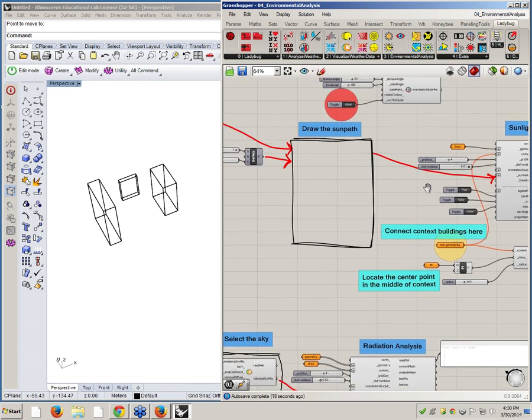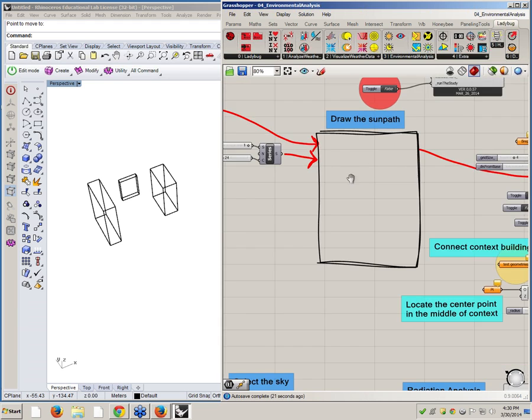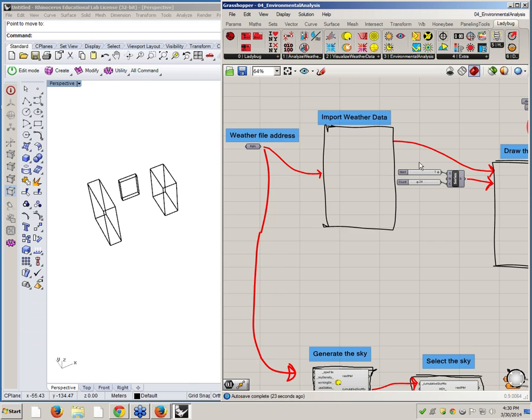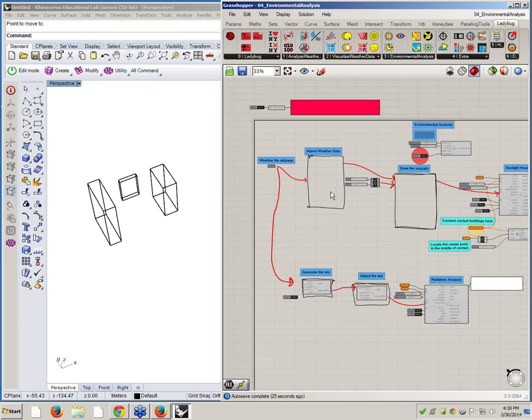What we want to do here, we want to run a sunlight average study, and a sunlight average study tells you how many hours of sunlight you see during a period of time, right? To do a sunlight average study, you need the sun vectors. Go ahead and generate the sun path and generate these sun vectors.